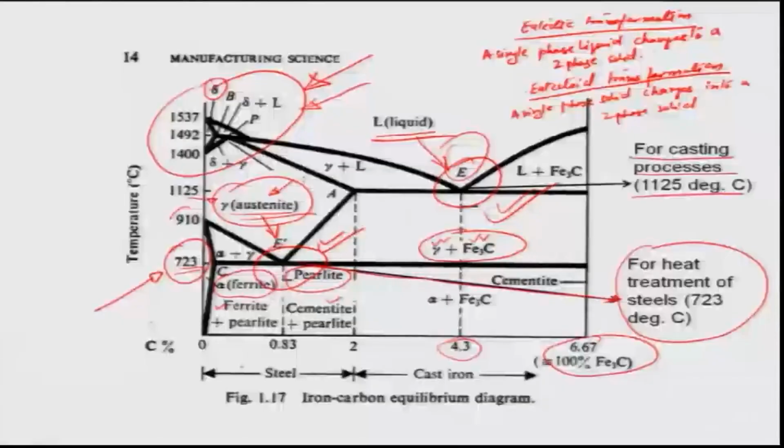So, basically again it is another case where the solid that is formed has a continuous distribution of both the ferrite as well as the cementite all through the crystal. Okay. So, similar to the composition here, a two phase solid, a similar kind of composition exists in this particular region, and this is known as pearlite. Okay. So, that is the eutectoid point.